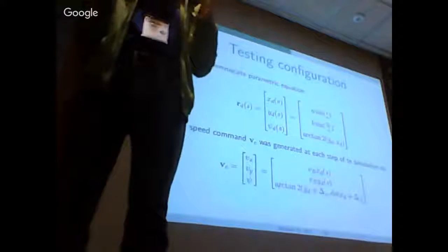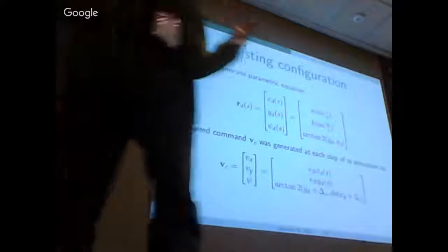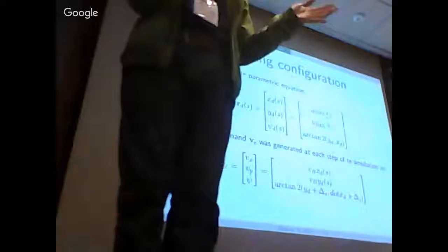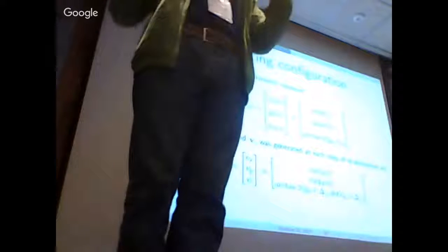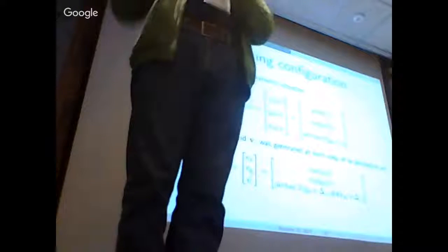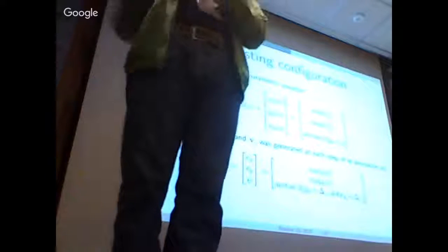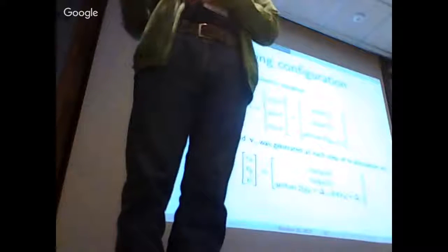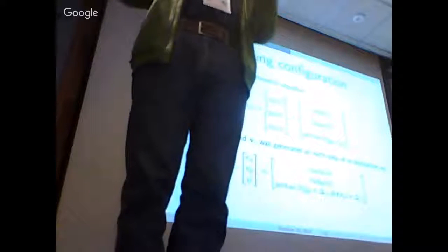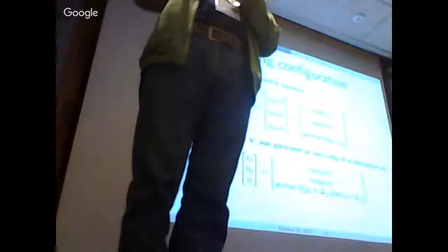Well, I really want to get this point across. The center of mass is moving in the commanded direction. The gait pattern, the position of each leg, each tripod, is defined at each iteration step. So that's what I mean when I say that the gait pattern is generated dynamically. And the equilibrium condition is only a step.